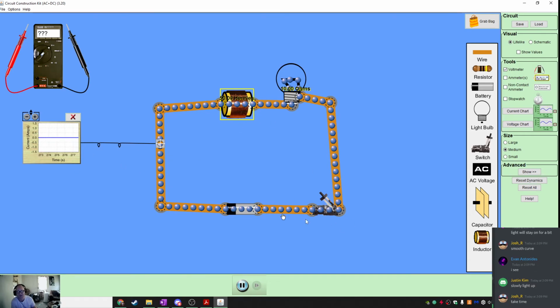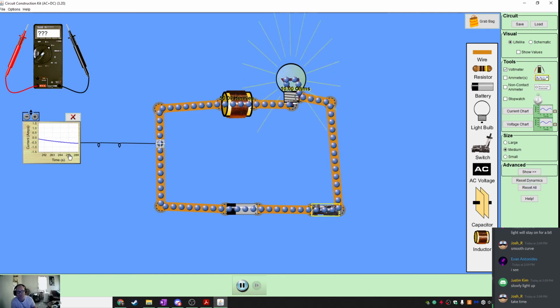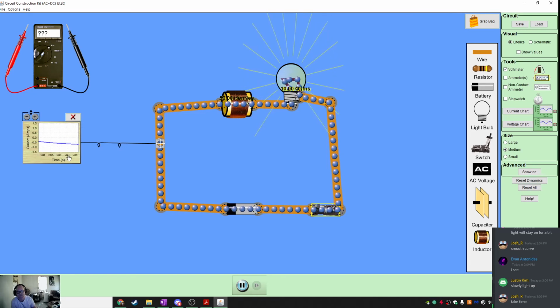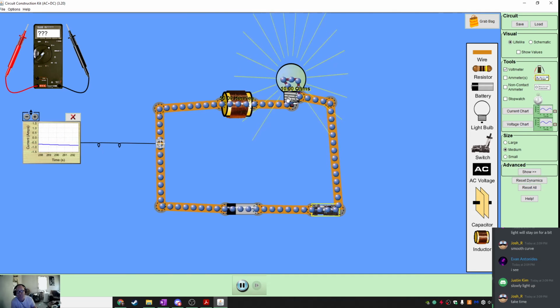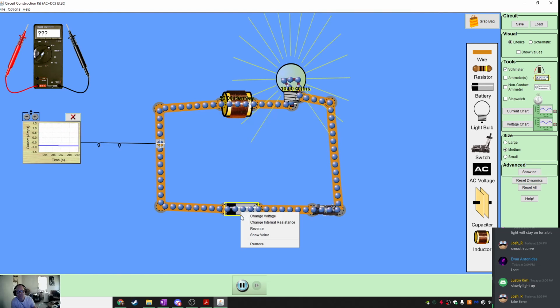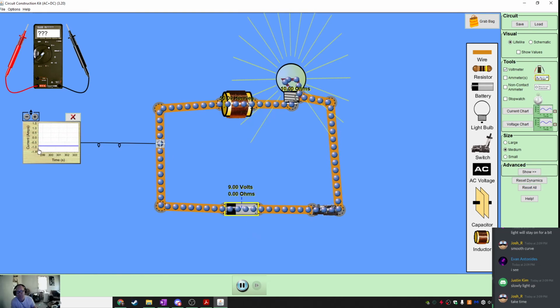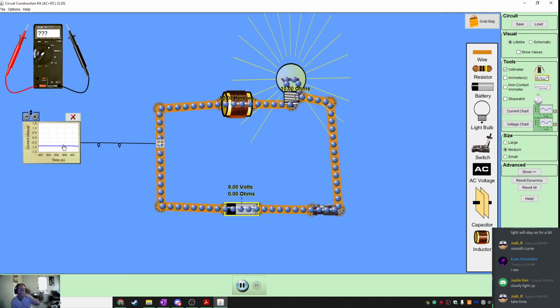So if I turn this on right at like 280, this should go up to about 25 plus 280, which would be 305, right? It should take till about 305 until we've reached maximum here. Maybe a little bit sooner. The max current in our circuit is going to be 9/10, and we're basically there at 90%. About 305, maybe a little bit sooner, but it's only so much.